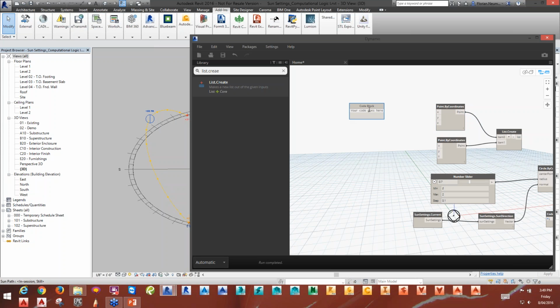What we type in here is 0, and then we start with a dot dot, and then let's say we count in X and Y, and then obviously we also want to influence a little bit our distance between our solar panels, and give them a little bit of an XY. Sweet. So we have here, let's call it an X count, and then we have a dot dot, and a spacing.